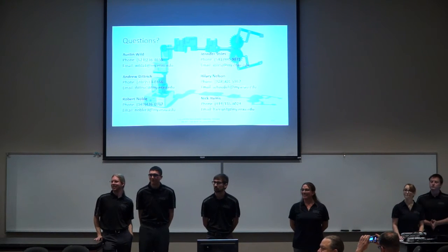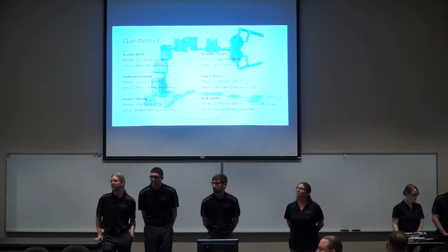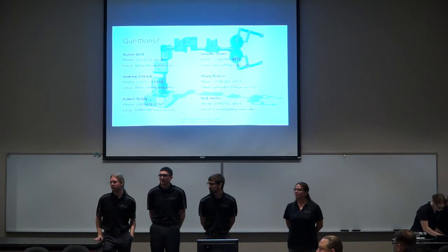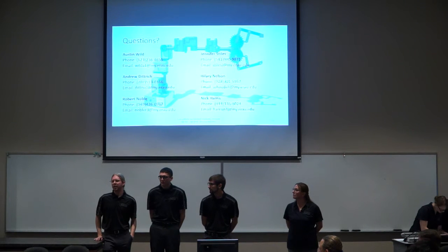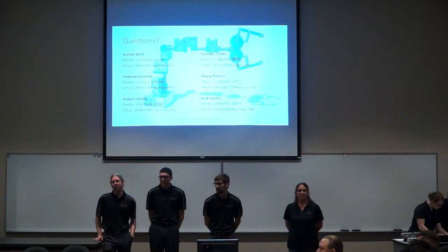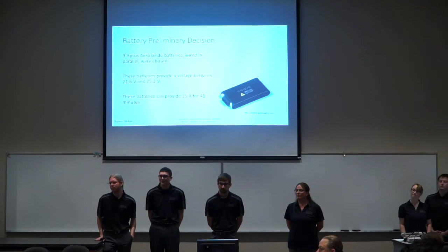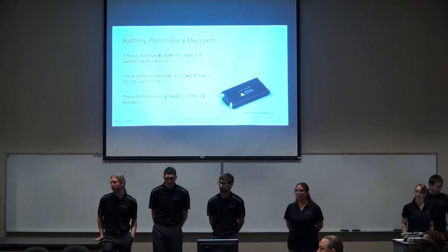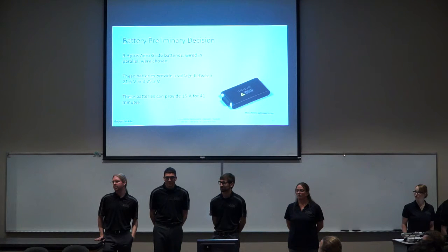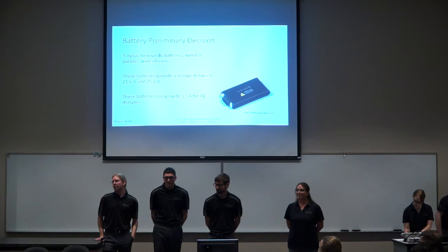Yes, I've got a question for Robert. You talked about the batteries that you selected. You said what they were, but what type are they? Lithium-ion, polymer? I believe they are lithium-ion. Okay, and it says you're putting them in parallel. Yes. How are you hooking them up in parallel to make sure you don't end up with a slight difference in voltage between the batteries that's going to cause a current surge when hooking it up? Do you have any sort of safety features on there? I did not consider that when selecting the batteries, I'm sorry.